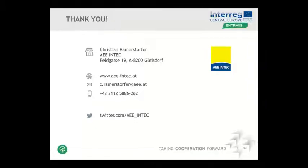Other options could be to use biogas instead of natural gas for your gas boilers. We had some plants with experience using vegetable oil instead of fossil heating oil. But this is sometimes a bit tricky. I heard about some experience where people were not so happy because you have to take care with vegetable oil. If you do not use this boiler frequently, you have to take care about the storage of vegetable oil because it gets solid at lower temperatures. So then it's not usable anymore. So you have to take care where you put your storage tanks. So there are some issues with the vegetable oil. But as I said, very nice standard solutions are 2 or 3 biomass boiler setups without natural gas.